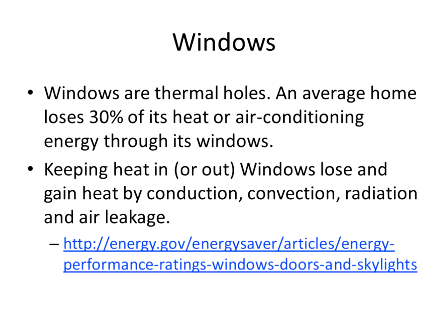And then for windows, you need to choose wisely. Windows are thermal holes, meaning that a lot of heat is lost with the windows. An average home loses 30% of its heat or air conditioner energy through its windows. So that is important. You can go to those links.